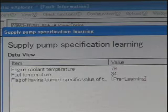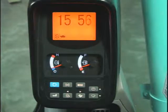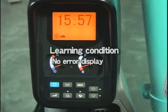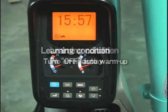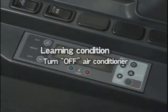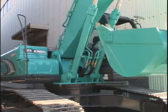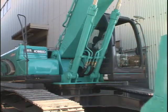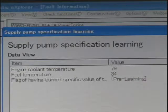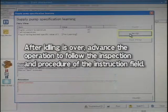The cooling water temperature is 60 degrees Celsius or more. The fuel temperature is 30 degrees Celsius or more. No error display. Turn off the auto warm-up. Turn off the air conditioner. When warming up is over, advance the operation following the inspection and procedure of the instruction field. Then click Next.